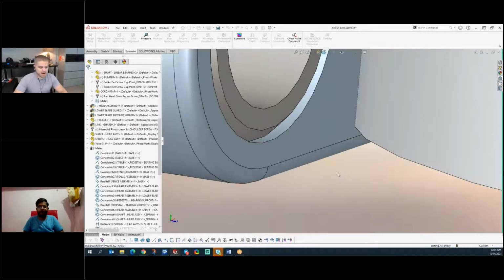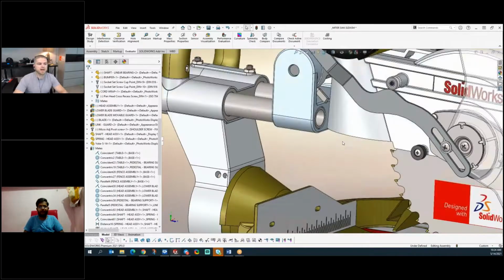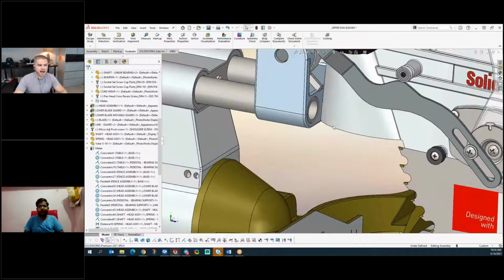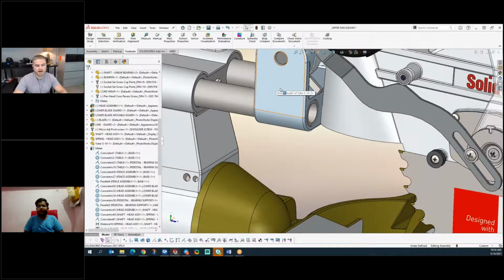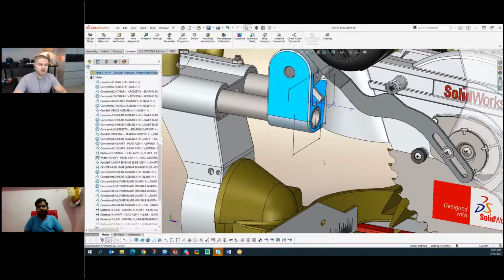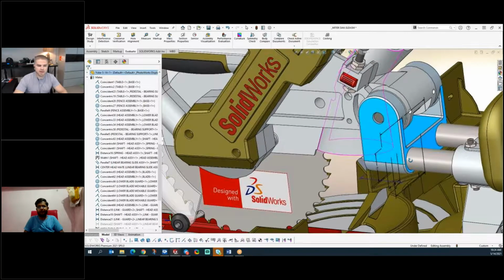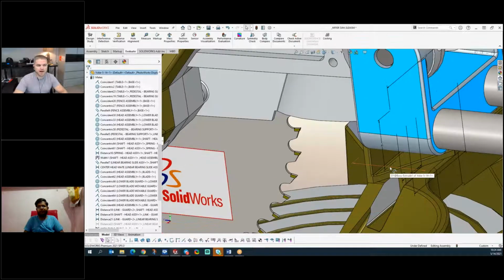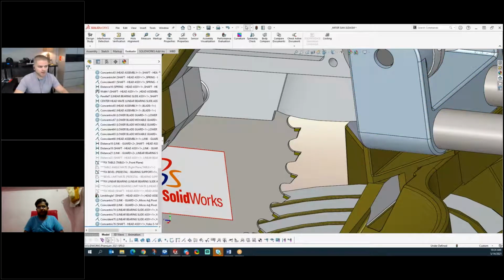So as a SolidWorks user, how do we deal with that? I can edit this part right here, in the context of this assembly. If I double click this part, here's all the dimensions that we use to create it, every sketch dimension, including this depth of 60. So I'll change that in this case to 40, and I'll rebuild my part here.